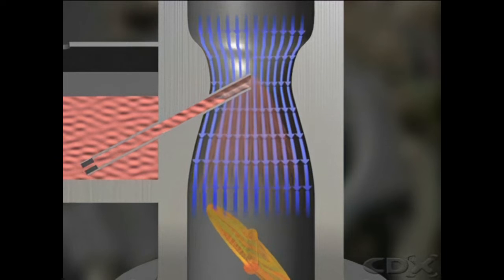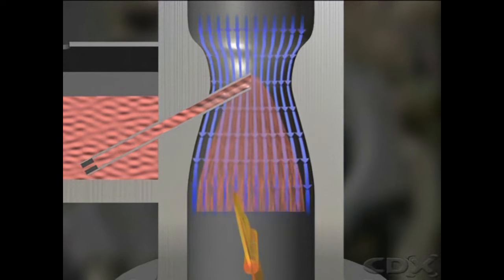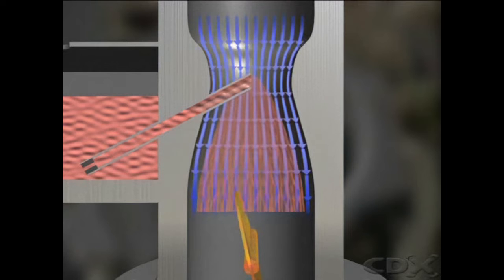Depressing the accelerator increases airspeed through the carburetor. This lowers air pressure at the nozzle. Atmospheric pressure on fuel in the float bowl stays constant, so more fuel is forced into the venturi to mix with the increased air. This keeps the air-fuel ratio roughly constant for a range of throttle openings.